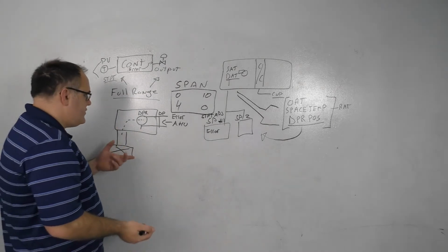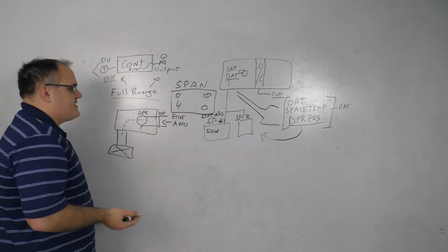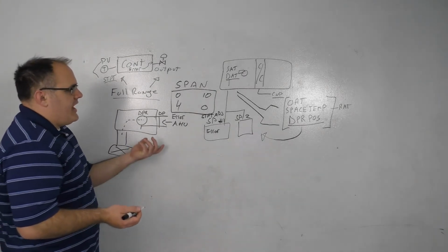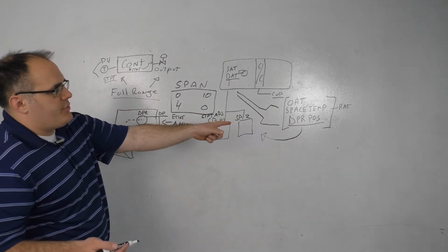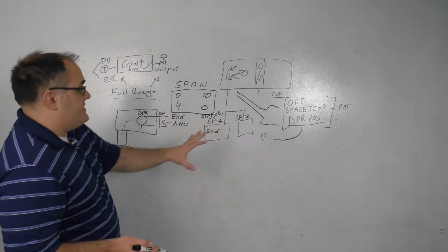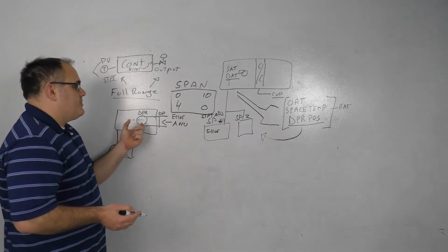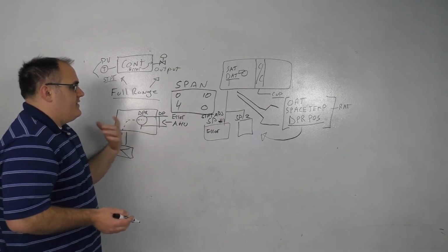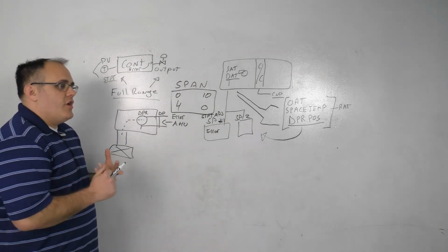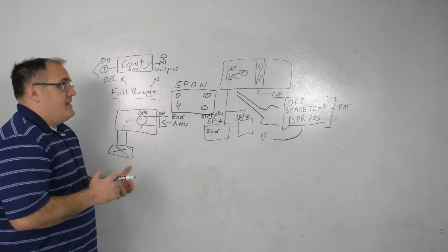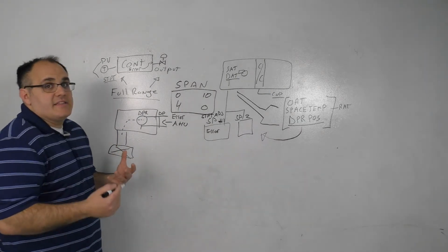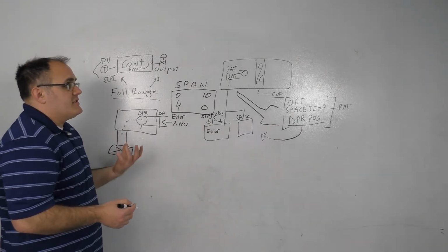Well, if a damper is 100% and you've got 0 or 10 CFM, that's a reliability issue, and you would throw out the damper position. You wouldn't utilize the damper position. If you have 100% and you have the right flow, then that indicates either a cooling capacity issue or a missized space. However, still, using damper position, in my opinion, has been more reliable than using space temp.